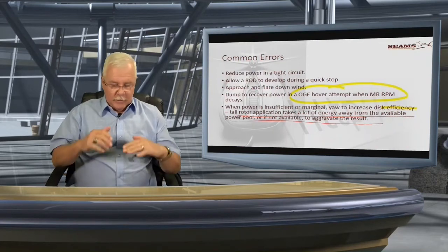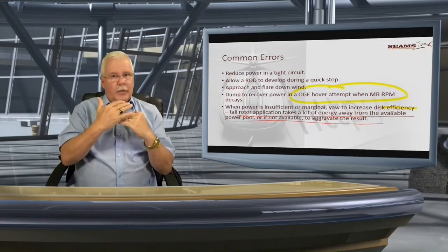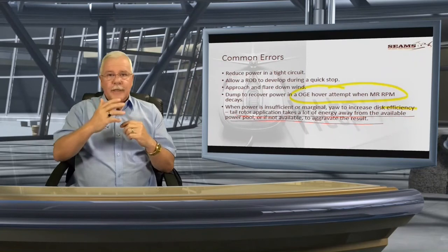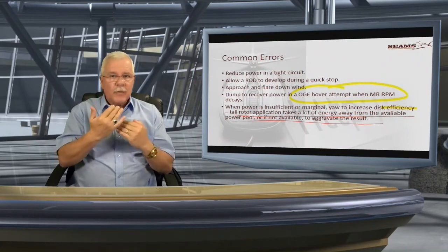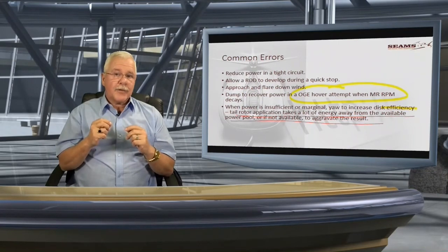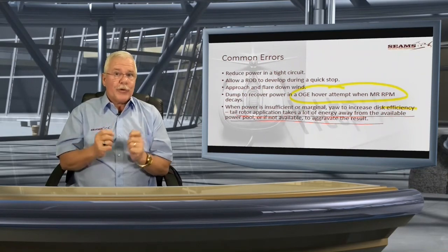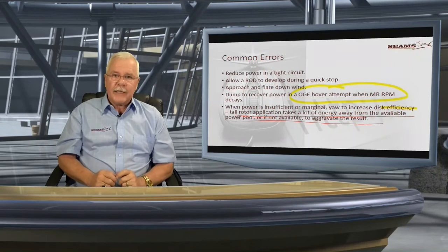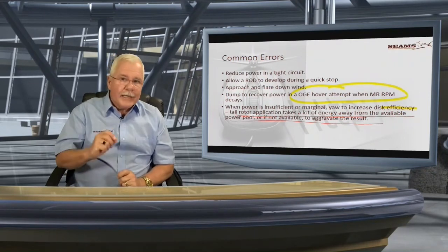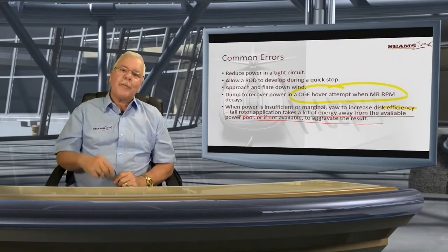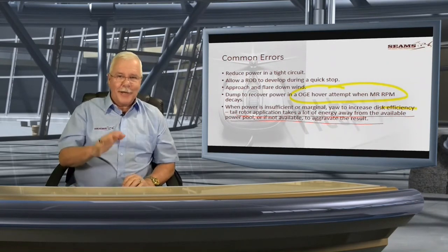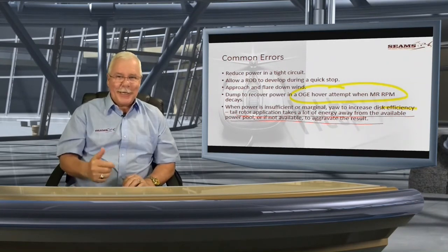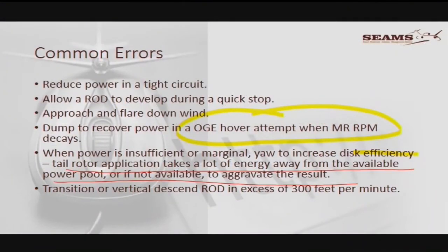Yeah, but Charlie, you don't understand. If I yaw this thing, then I get more effective. Your blades are stalled. When the blades are stalled, it doesn't matter whether you're turning. It will make it just more stalled or less stalled, but it's not going to unstall it. The net effect is not big enough. That is not your problem. Your problem is to get out of the dead air. Sorry, I know I'm a little bit pertinent, but I got to get this thing down.